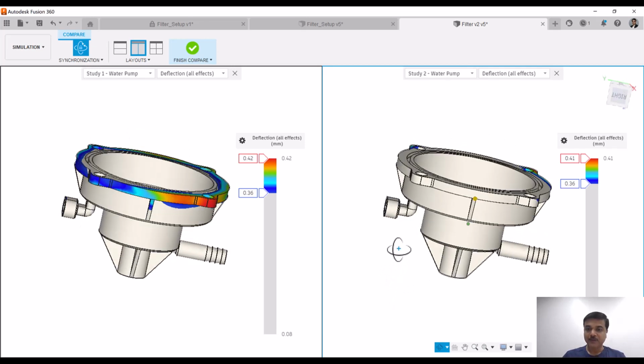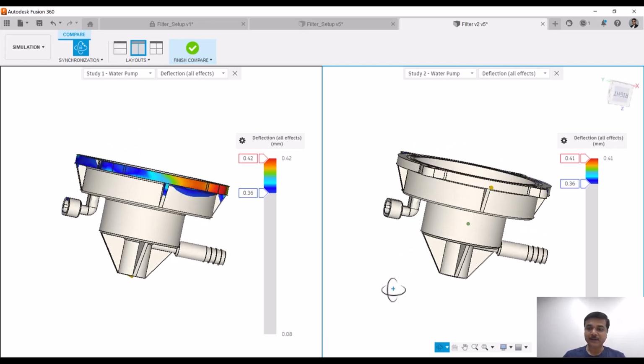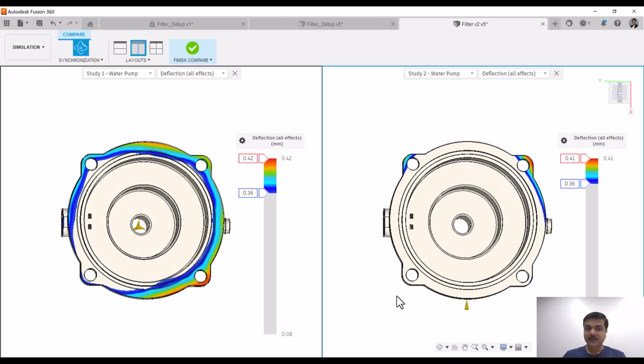So that was pretty helpful. By just changing the gate locations, I would be able to do it. So I hope this demonstration, which took a little longer, was useful, but you can do the comparison of multiple gate locations or materials as well, and try it out.